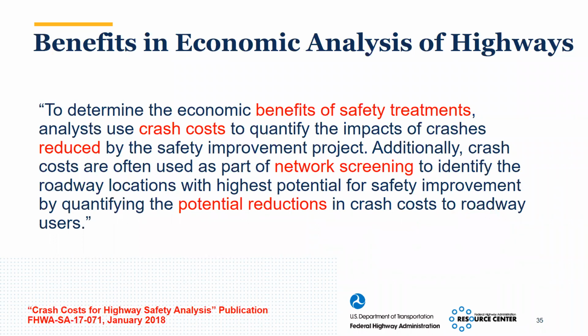tool specifically. When we talk about benefits, so if we're doing a benefit cost analysis, when we talk about benefits in this context, we're talking about essentially the benefits of reducing crashes compared to some sort of base condition, could be a no build, could be the existing. And then for reducing crashes, we need to have crash costs for each type of crash, each severity, based on severity levels, to determine what the reduction in crash costs are for that safety improvement